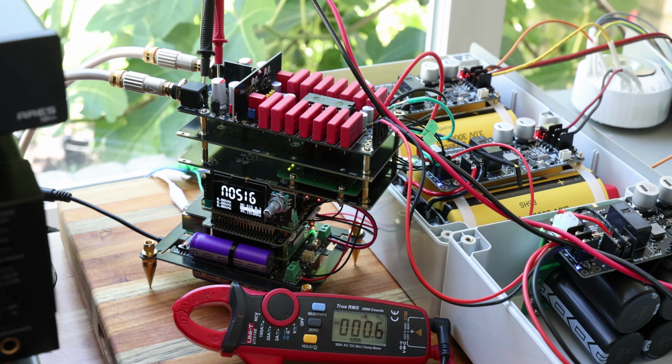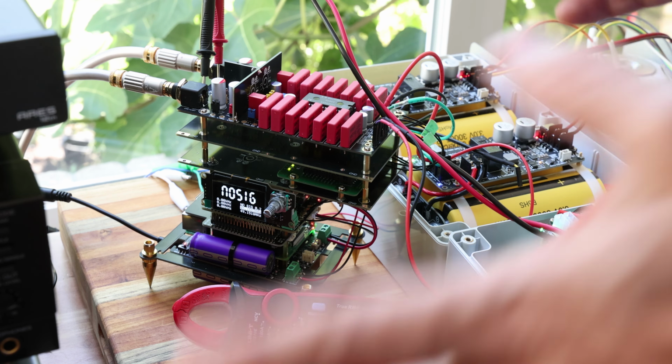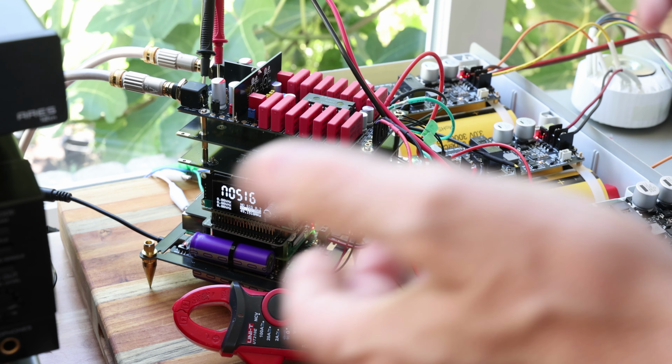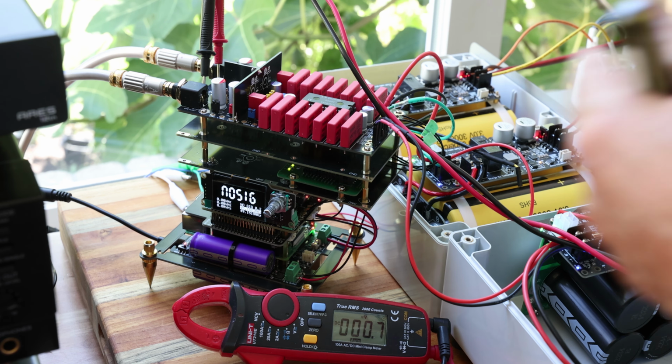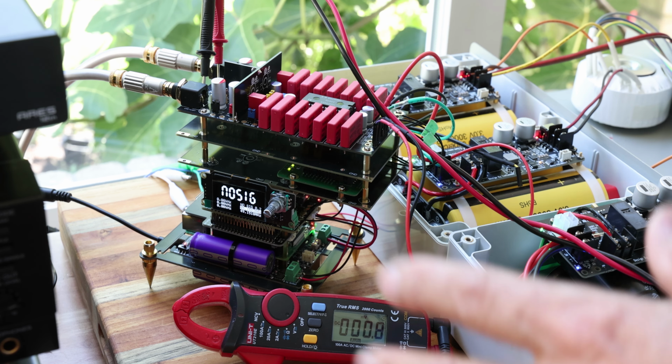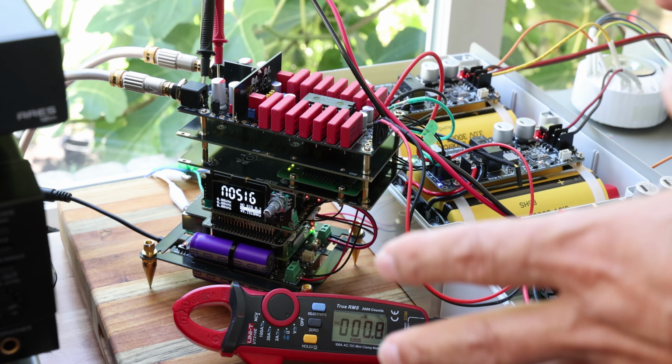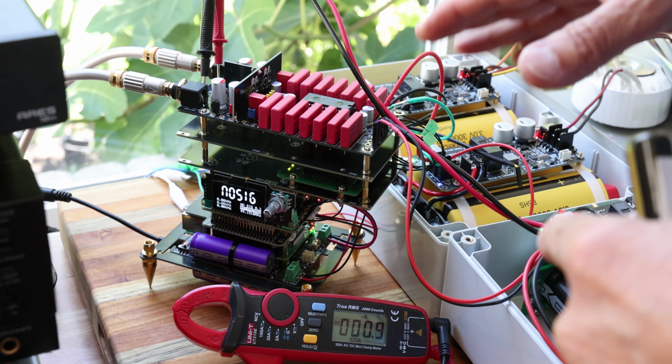And then the power sequence should be to power up your FIFO Pi streamer first, wait a little bit till that's going, and then start your TD1 DAC power after that. This way you're going to have the least amount of popping noises, the least amount of initial DC offset, and the most stable DC offset all along.